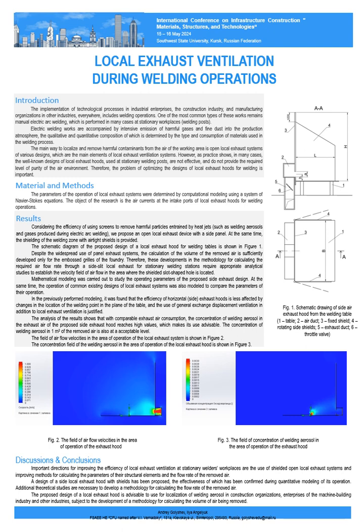A design of a side local exhaust hood with shields has been proposed, the effectiveness of which has been confirmed during quantitative modeling of its operation. Additional theoretical studies are necessary to develop a methodology for calculating the flow rate of the removed air. The proposed design of a local exhaust hood is advisable to use for localization of welding aerosol in industrial enterprises, subject to the development of a methodology for calculating the volume of air being removed.